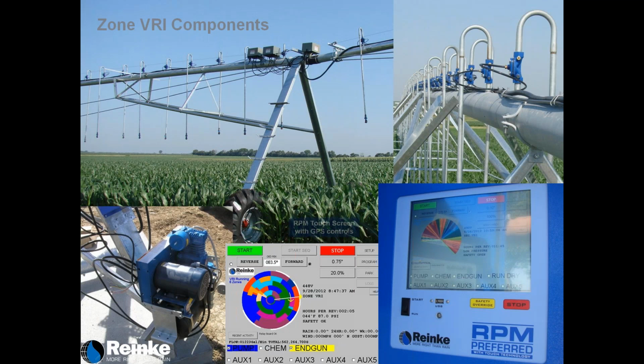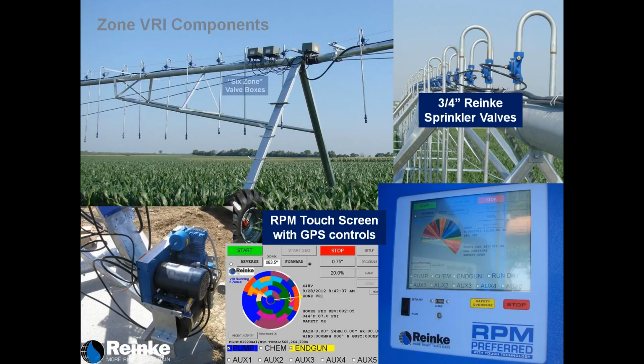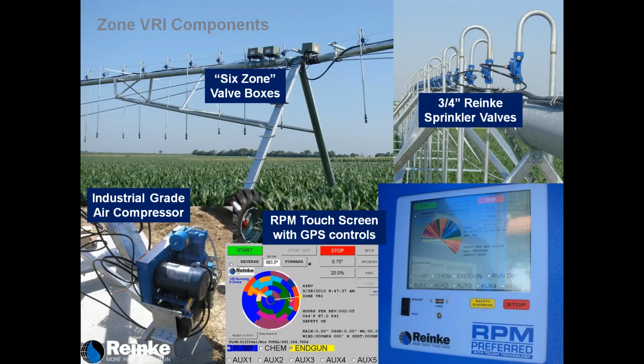The components that are required for zone VRI, other than the touchscreen and GPS, we use what we call our Reinke sprinkler valves on every sprinkler that's going to be in a zone. Our zone boxes, or valve boxes, contain 6 zones. So with 84 zones maximum, that would be a maximum of 14 valve boxes that could actually be placed on a system.